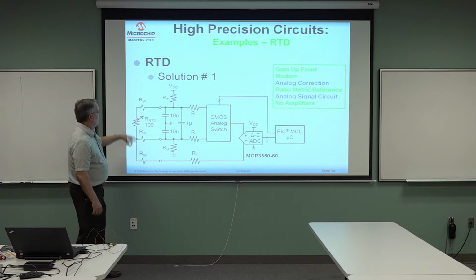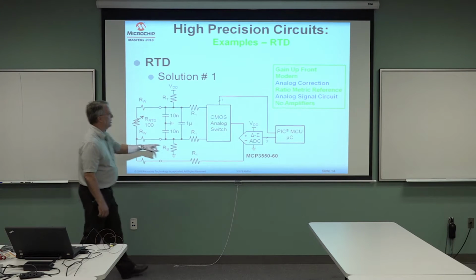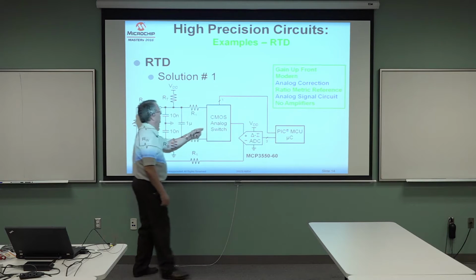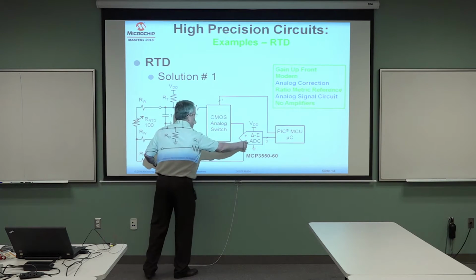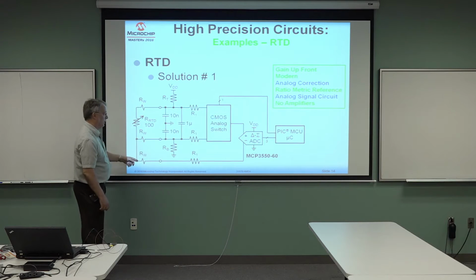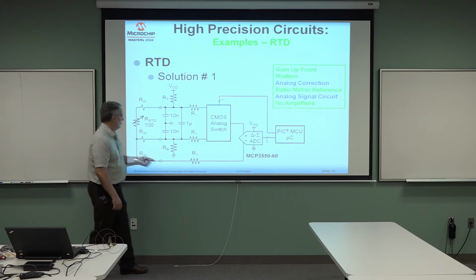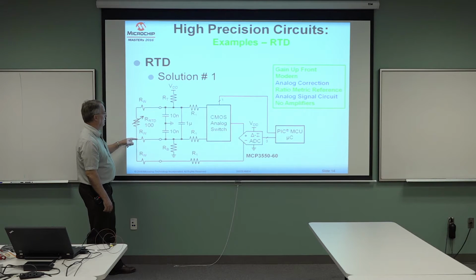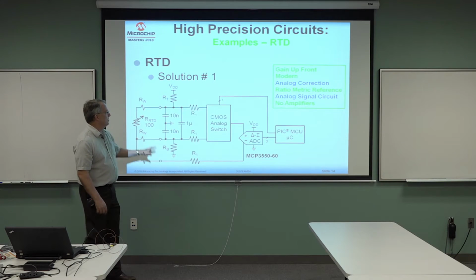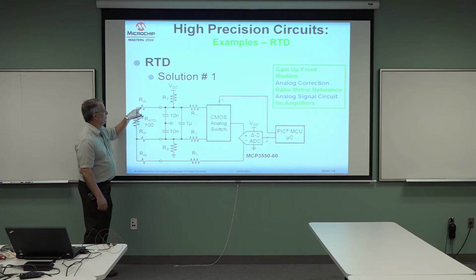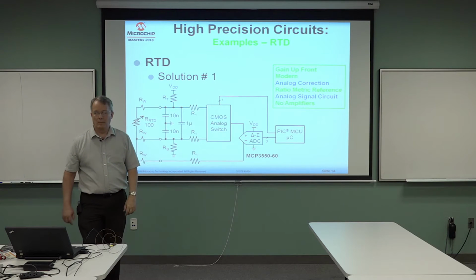So why do I have 3 legs here? Because I can do this switch. I can measure here, I can measure here, and then the Del-Sig converter with its minus input will differentially reference everything to this input here, which is basically an open circuit. So therefore it'll measure this voltage, and this leg will get a voltage drop. So this is a way that you can, in firmware, correct for the wiring resistance drops.